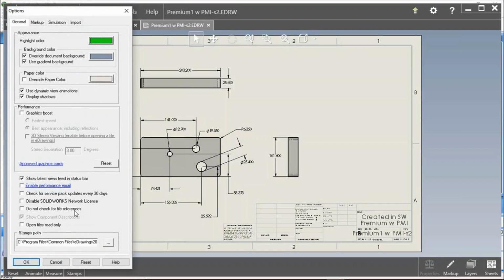One other thing to note when looking at drawings and assemblies, like in SOLIDWORKS, you have those references there. So if you open a drawing where the part file changed but the drawing hasn't been updated yet, that's viewing the actual SOLIDWORKS drawing. It can give you a watermarked message telling you that the file may be out of date and that you should go in and update the drawing file to match the part file. So that option is within eDrawings when viewing the actual SOLIDWORKS files themselves.